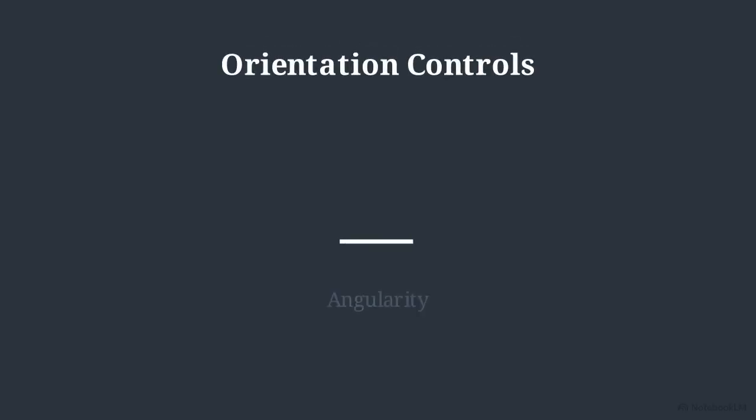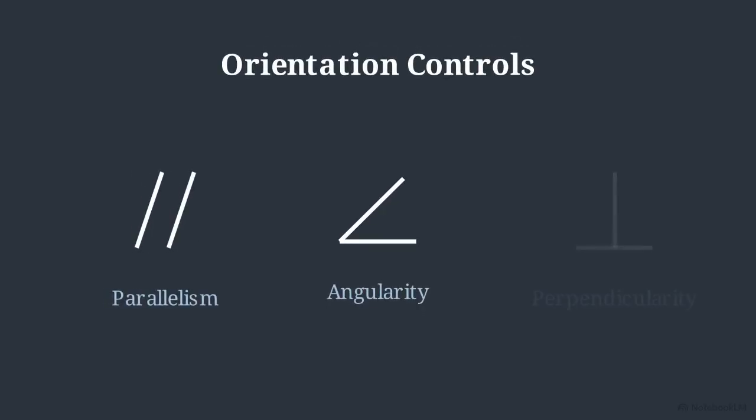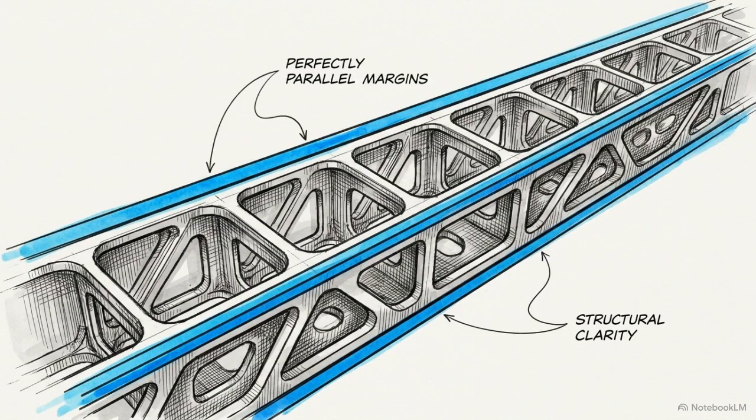To eliminate that expanding margin of error, we use the GD&T Angularity control. It belongs to the orientation family, sitting alongside parallelism and perpendicularity. Securing large, interconnected assemblies requires using rigid, linear boundaries. This method maintains a constant error margin across the entire length of the feature.